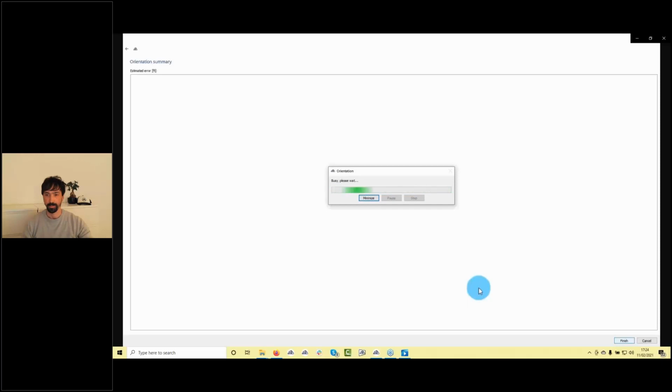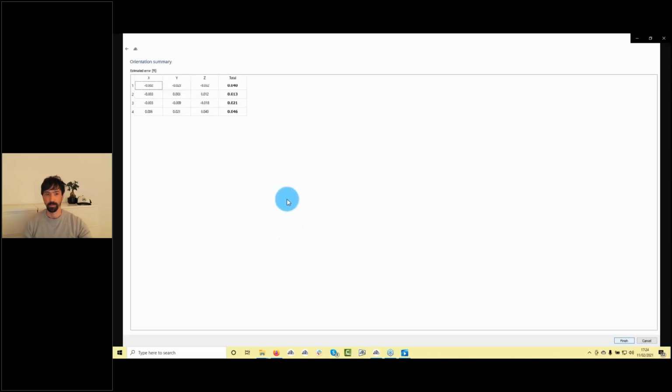Maybe just in the meantime, if you don't have a Phantom 4 RTK or Matrice 300 with an RTK on it, we always advise to use a minimum of 3 GCP points per project, but to have good control over it, it's great to have 10 ground control points per battery. So you can cover really great results already with this area, and it's super fast altogether.